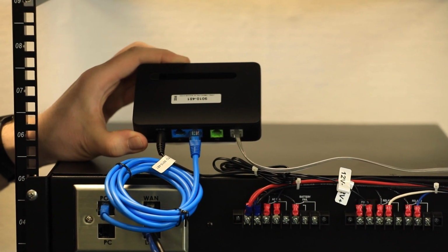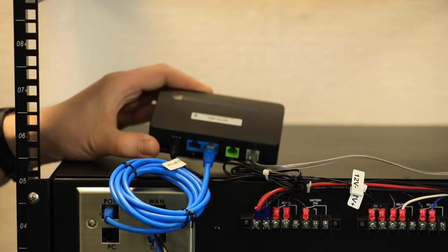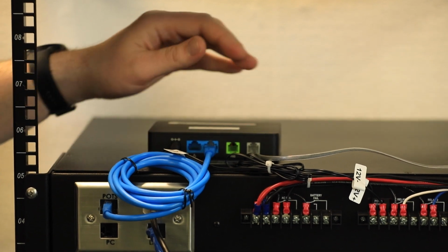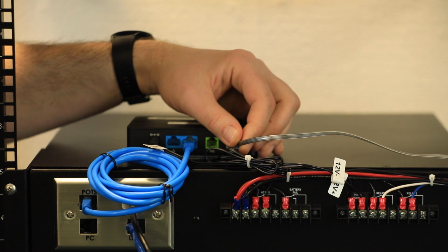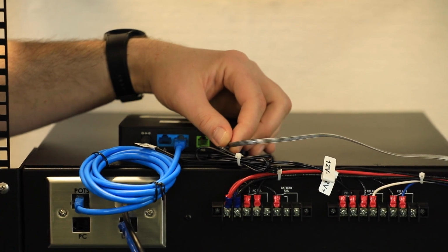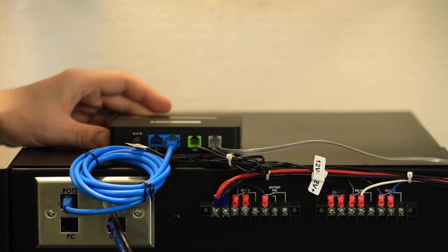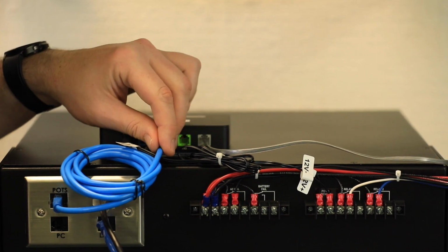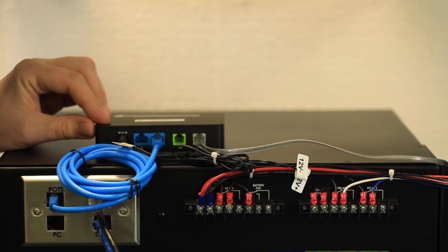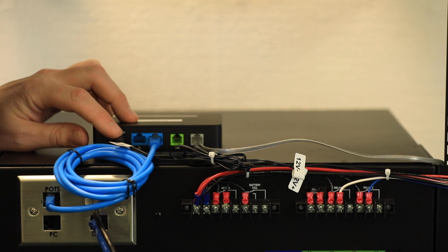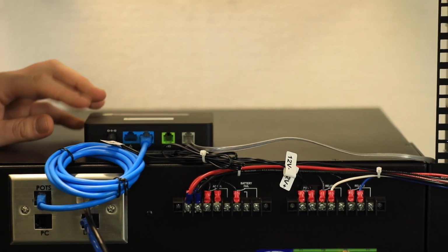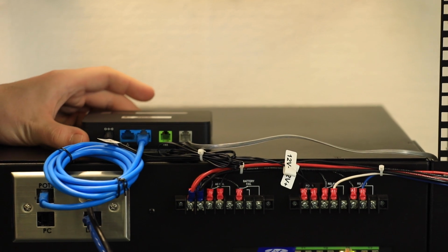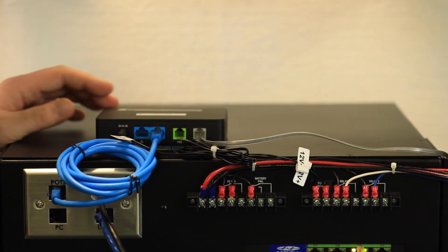To allow the system that capability, an auxiliary modem needs to be added. It's going to be our POTS-4800S modem. All it requires by the installer is to provide the RJ11 telephone line used for it to dial out on. Cornell includes the data patch cable to allow it on our network, and also a power connector to provide 12 volts DC power. Typically the modem mounts on top of or adjacent to the main head-end unit here.